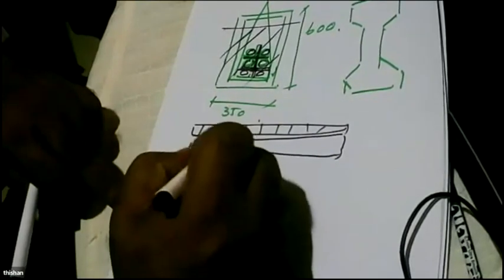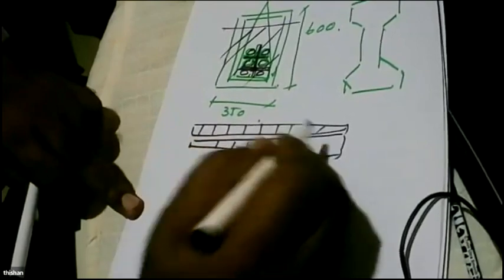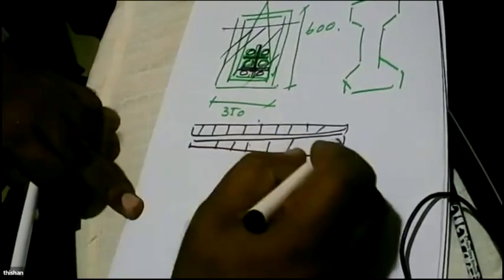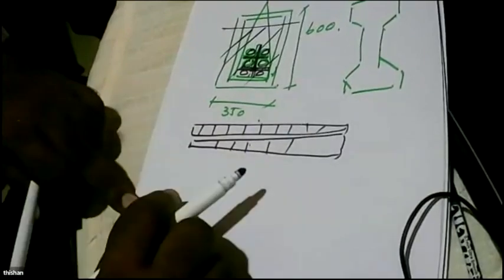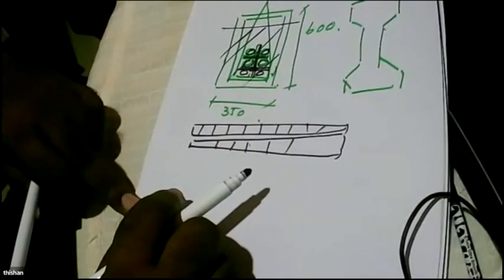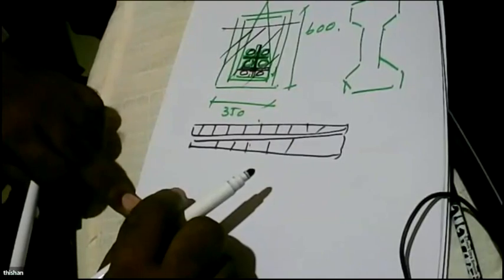And when you are using the bamboo, you don't clean it too much, so that it will be a little rough. And there will be good bond, because it's tapering in two different directions. And actually bamboo can contribute to the tensile carrying capacity needed in the beam. And you can get a lighter beam, but which has a higher flexural capacity.